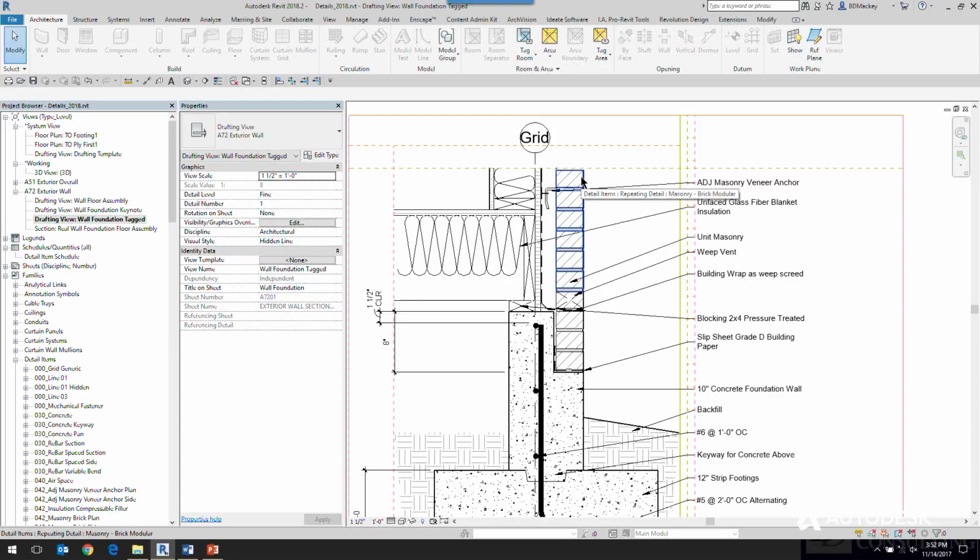A lot of times I'll have filters built into my visibility to say, anytime any of these components has "beyond" in the comments, half-tone it. So I'm building more intelligence like that. When something is beyond, I don't have everybody right-click, override graphics and views, and say I want to use color 250, or I want to use white, or I want to use purple. So I gain that consistency with filters based on maybe a property somebody puts in there as well.